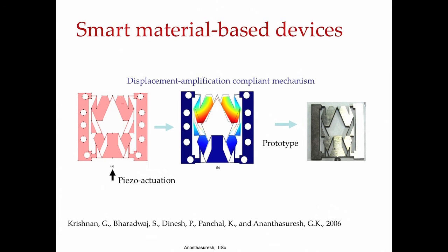The idea here is, let us say I want a device to be operated with piezoelectric actuation, which gives very small displacement of the order of, let us say, a few microns, and there will be enough force that you can use that force, as you can see in the compliant mechanism in the middle figure here. This movement you hardly see, whereas here you see what was there has moved from there to here. Okay. It is able to retract when you apply the force here.